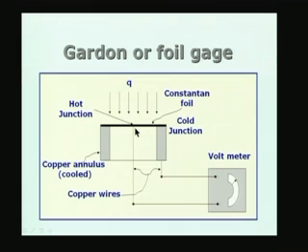Okay. So, what I have is a temperature variation along the radial direction here, and in a little while we will find out how it varies, what is the relation to Q and the various dimensions of the sensor and so on, by a simple analysis. So, the point is that the Q which is to be measured is now converted to a delta T between the center of the foil and the periphery of the foil, and that is measured by a millivolt, which is the conversion of temperature now to an electrical signal by thermoelectric phenomena.